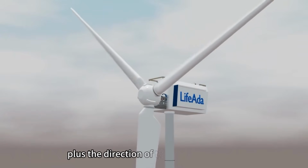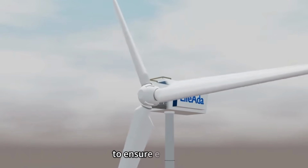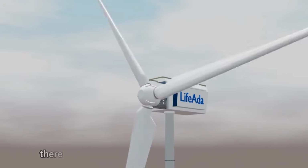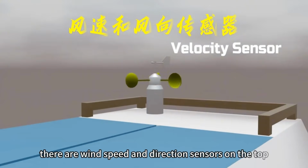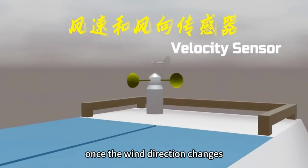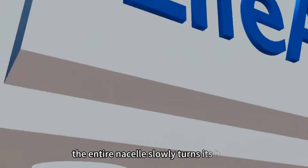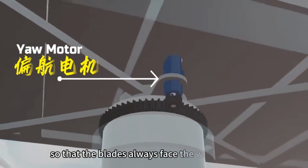Plus, the direction of the wind is not fixed. To ensure efficiency, the wind turbine must always face the wind. Therefore, there are wind speed and direction sensors on the top. Once the wind direction changes, the control system will drive the yaw motor. The entire nacelle slowly turns its head, so that the blades always face the wind direction.